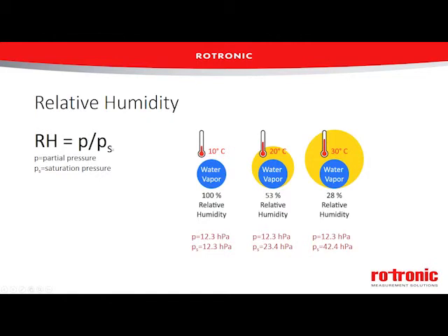And if we look at the formula for relative humidity, partial pressure divided by saturation vapor pressure, it's like any fraction. When the denominator varies, even if the numerator stays the same, you're going to get a variation. And that's one of the big problems people have with measuring relative humidity, because the temperature is not uniform. Relative humidity is relative. That's the key. Many times people ask about or talk about humidity, they really mean relative humidity.